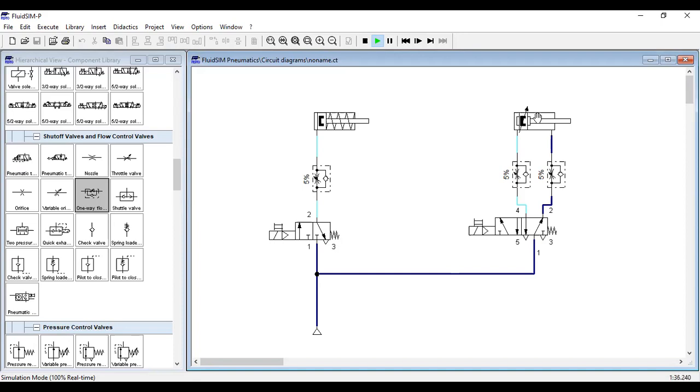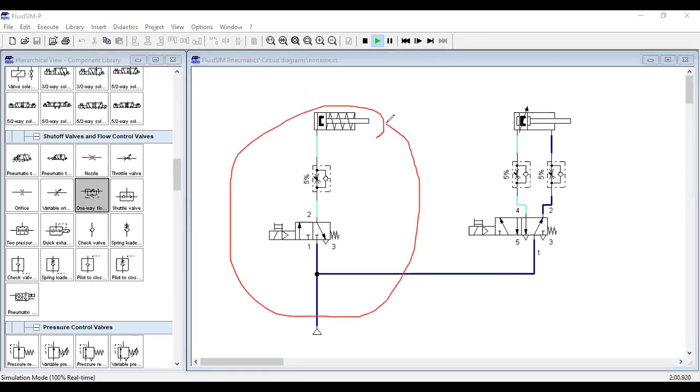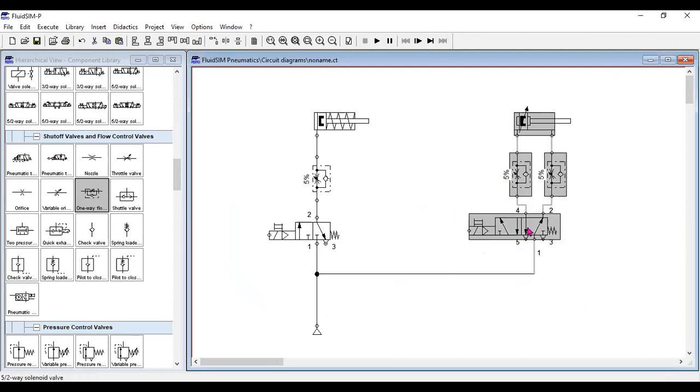So take note, the double acting cylinder and the single acting cylinder can replace each other, provided that the double acting cylinder uses the single coil type. Which means the operation of this single acting cylinder can be replaced by this one or vice versa. Now we'll try to take a look at the other type of 5-2-way.